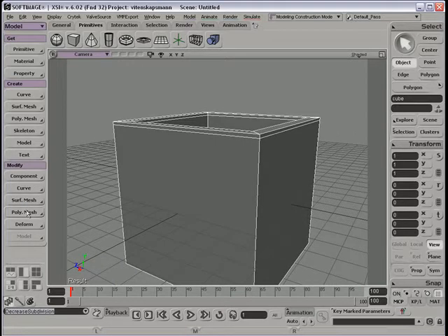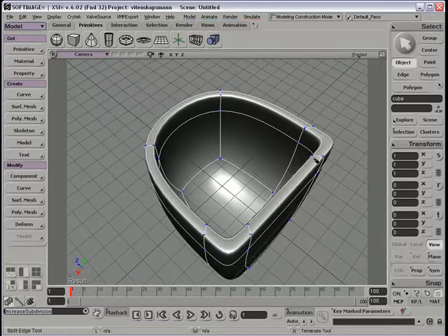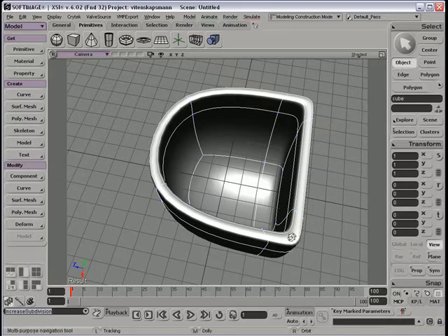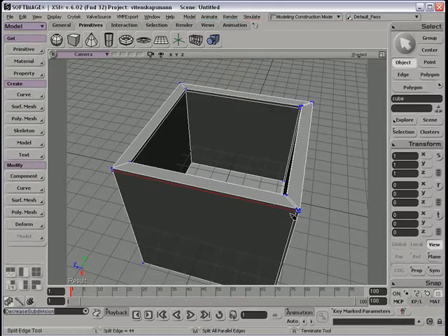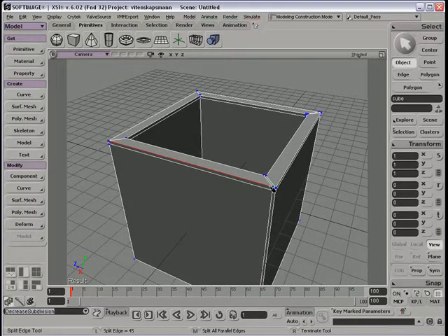and then you middle mouse click on modify poly mesh, and that will reselect the last tool you selected. And then you go here and you middle mouse click and release. And here you can see now this has become a straight line, but you can see it has a little bend. So we go with the minus key again, and then we make another cut.